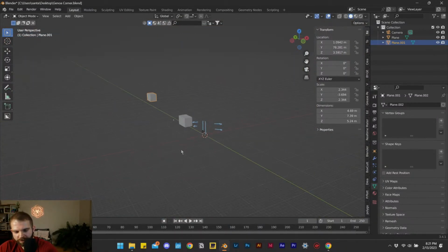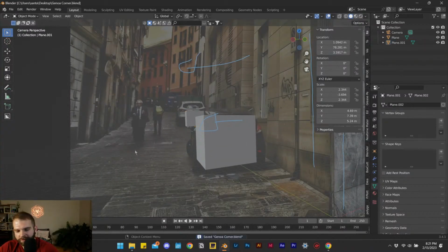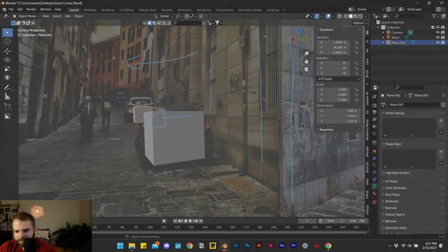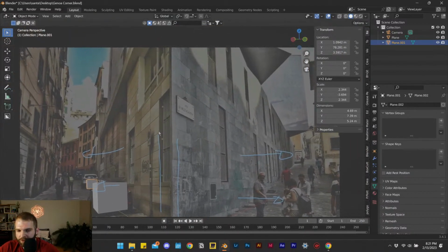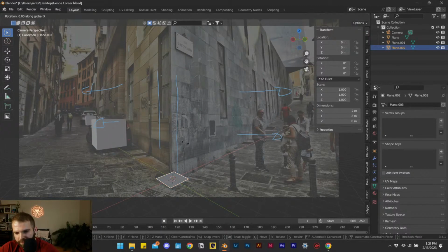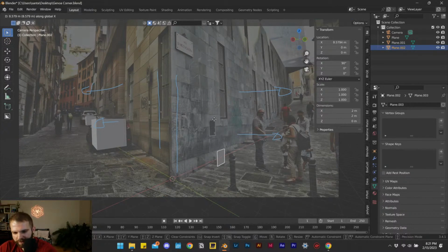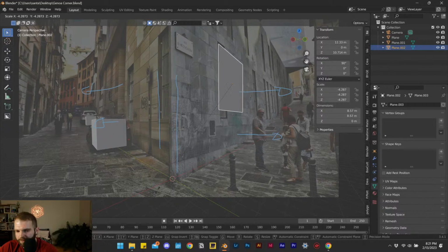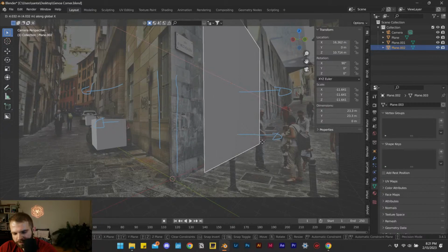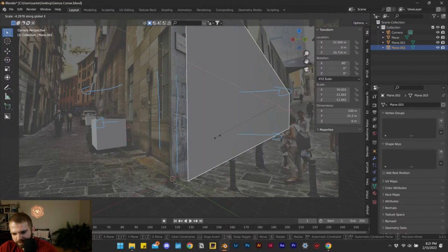So we can see how these cubes are now positioned in 3D space, and it doesn't look like much, but in the photo, it looks like this, right? What that gives us is a reference point. So if I now drop in a wall or a plane, I can rotate it on one axis 90 degrees, move it along that axis, move it up, and I can build out this wall, and start using its dimensions or its subdivisions as a way to build out this wall. So I can go ahead and stretch it.